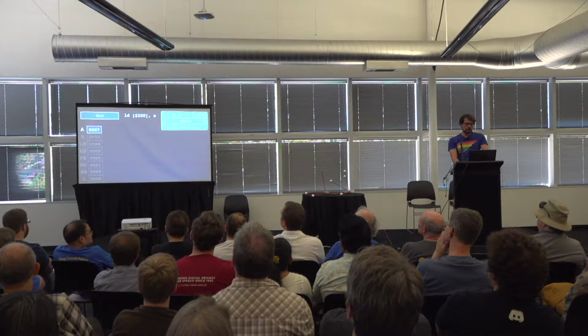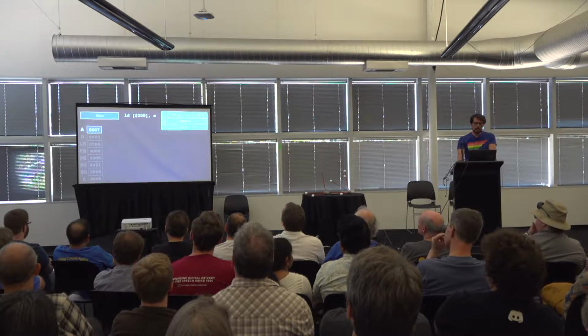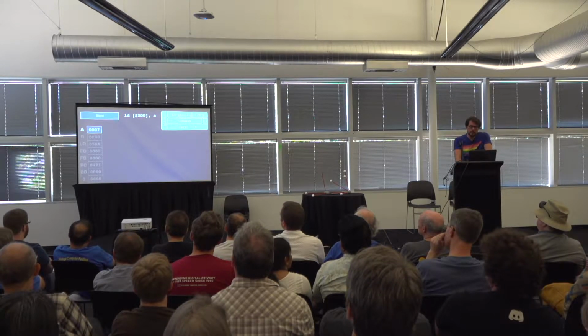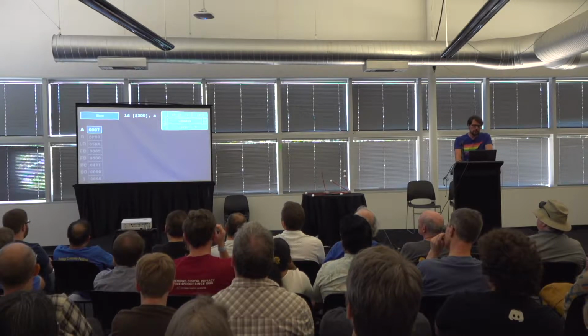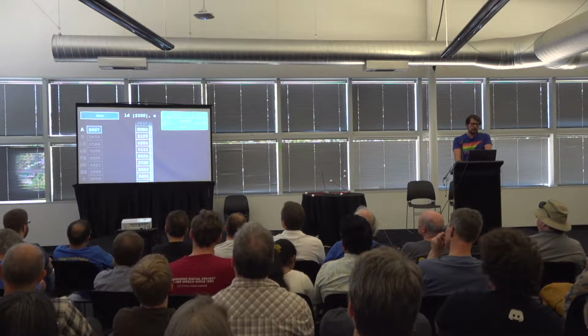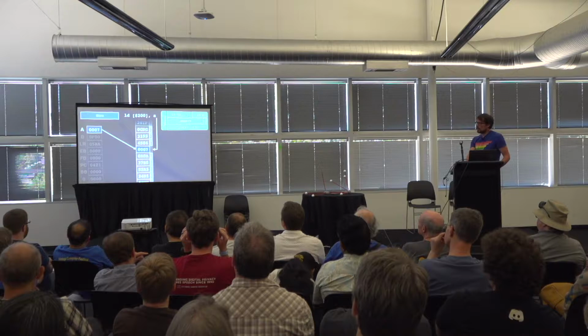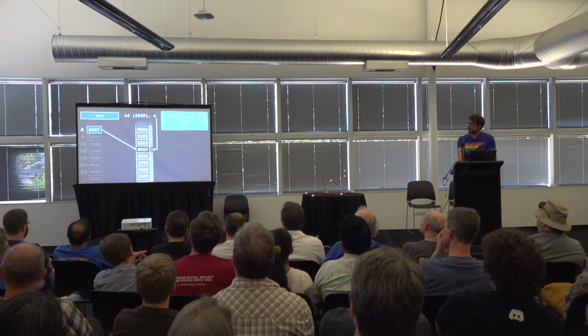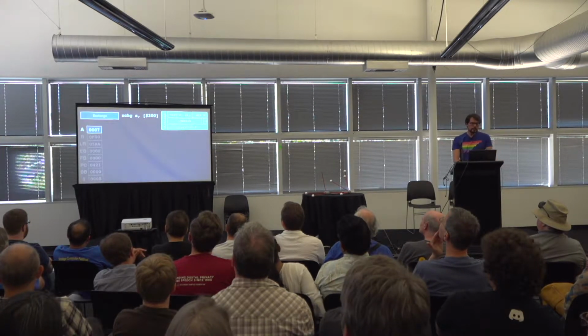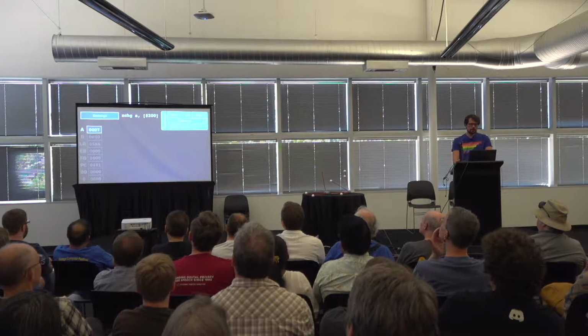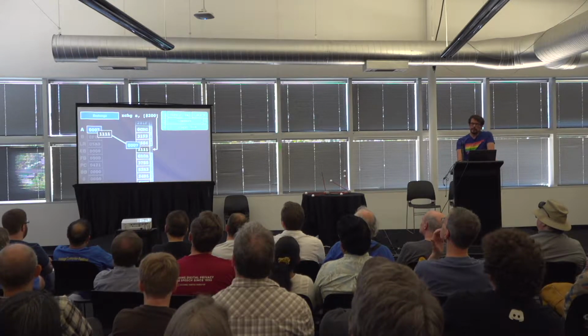This is the store instruction, store indirect 200, A. Like with all instructions, the first argument is the destination, memory, and the second one the source, the accumulator. It looks up address 200 in memory and copies the contents of the accumulator into that cell. There's also an exchange instruction, which can atomically swap the contents of the accumulator and a memory cell.